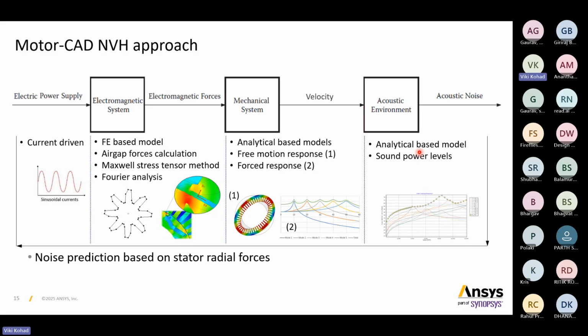So you have to apply various conditions to the motor, like changing the geometry or the shape of the poles, or sometimes using the skew method to reduce the power levels. Reducing the power levels means reducing the sound level, obviously. And all this noise is due to the stator radial forces in the motor.